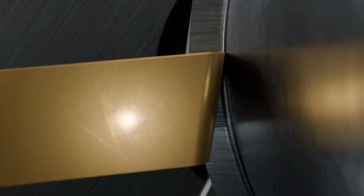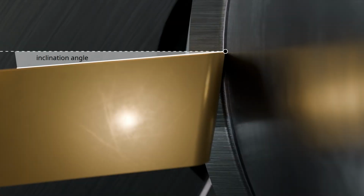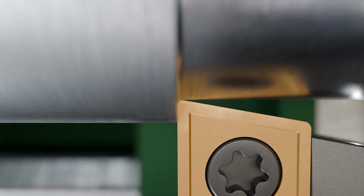In addition to viewing the indexable insert in the radial direction to define the rake angle, and in the axial direction to define the inclination angle, we now look at the insert from above. Here, another geometric angle can be defined, the so-called nose angle epsilon. This angle is formed by the main cutting edge and the secondary cutting edge. The larger the nose angle, the greater the stability of the cutting edge and the lower the risk of cutting edge breakage. Furthermore, the increased surface area improves heat dissipation and reduces the thermal load on the cutting edge, which in turn positively affects tool life.